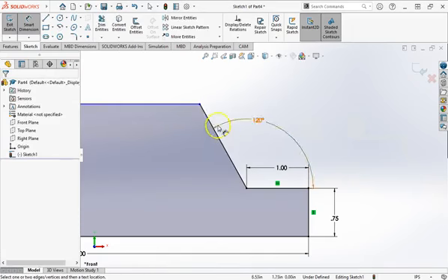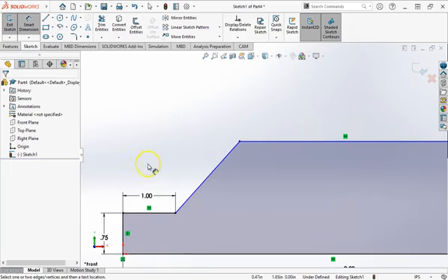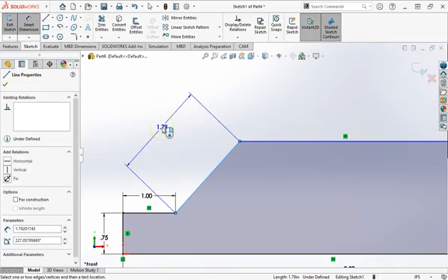Now to do these lines that are at an angle, this is one method using the degrees. Now, if I were to dimension this line, there's another way you can do it. So if I click on this edge, you'll see I can get a whole bunch of different dimensions just by moving the mouse around. So now this one is not an angular dimension. This one's a little bit different. But notice where the mouse is sitting right now. What I'm measuring is just the basic length of that line.